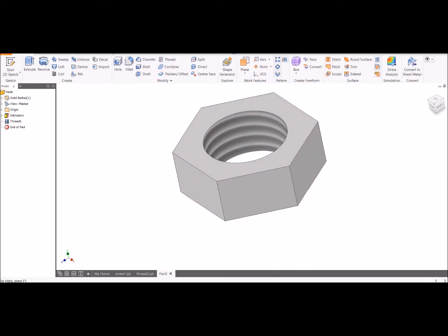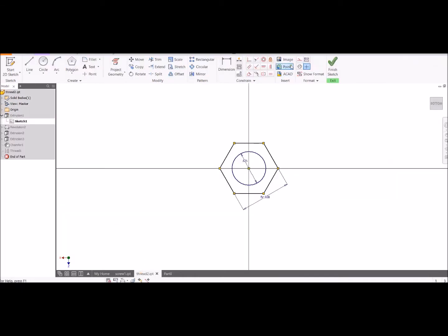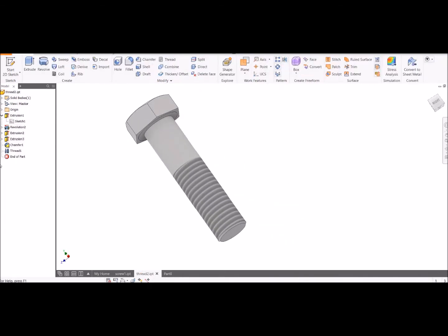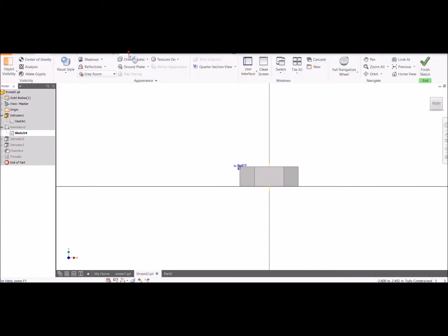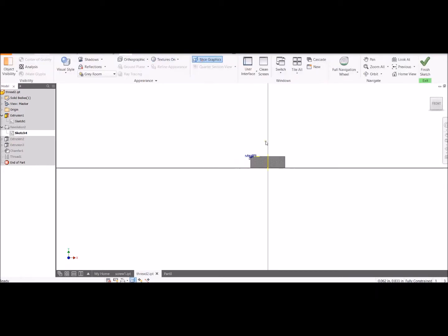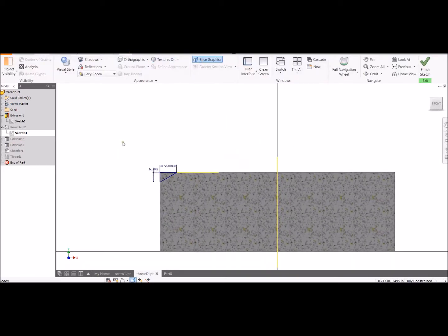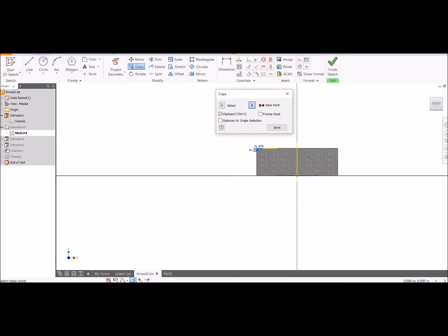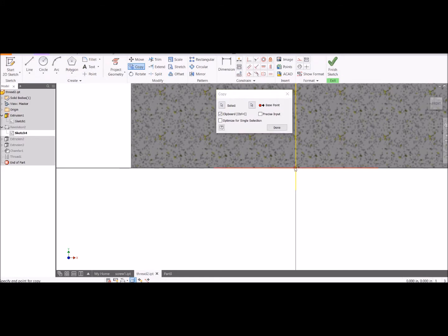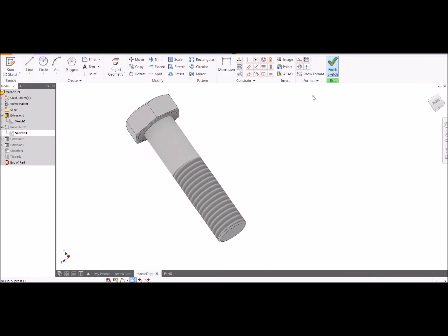And we can go back to the previous file. Let me exit out of that sketch. I'm going to copy the sketch I created for chopping the corners off of here too. Remember, View, Slice Graphics opens it up so I can zoom in and see that little corner. And again, copy these guys with a base point and onto the clipboard if you want to bring them into another file. So I'll just use the origin, which is usually a good spot to get that base point from.